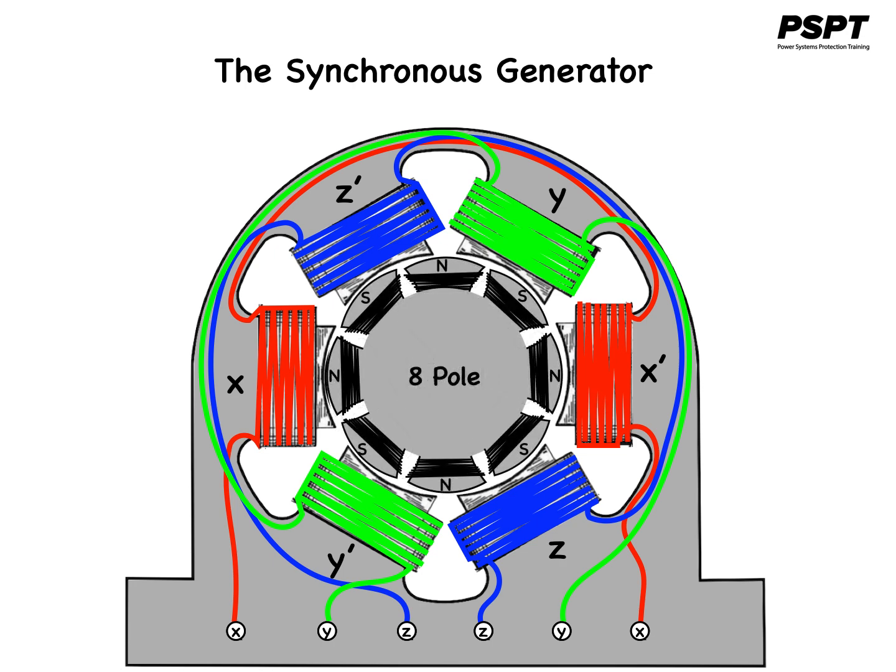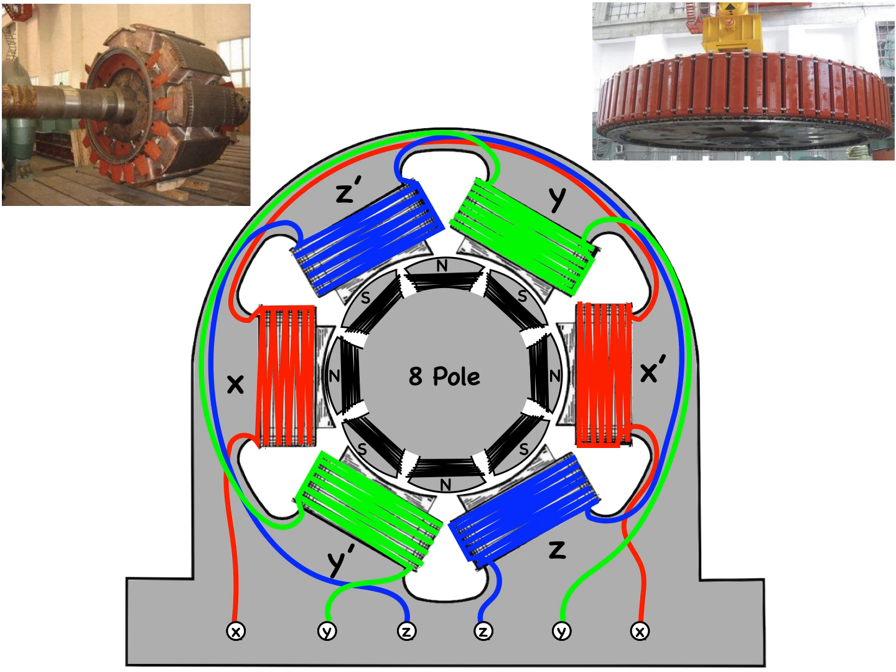An 8-pole rotor would look something like this. Again, notice the alternating north and south poles as you go around the rotor faces. Salient pole rotors are usually of large diameter and shorter length. They are typically used in lower speed electrical machines, say 100 RPM to 1500 RPM.